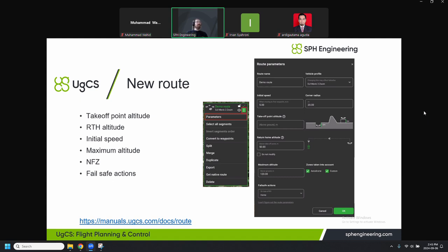And the drone understands only relative values. So in this case, all the flight altitudes will be shifted by 2 meters because by default, the drone assumes that it's taking off from the ground. So in order to avoid this, we can set a positive or negative altitude. So for example, if we're taking off from a 2-meter bus, we add 2 meters. If we decide to quickly dig a well and take off from there, then we add a minus, for example, minus 2 value from there.